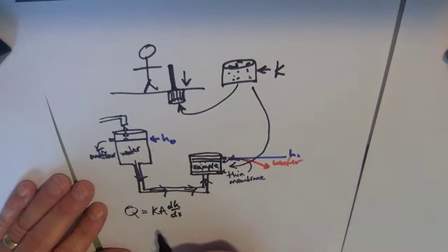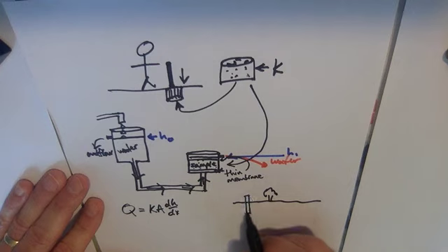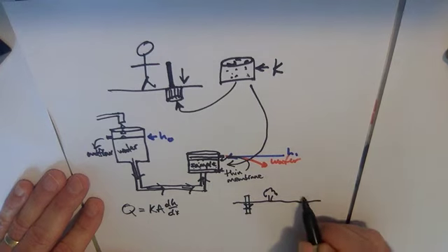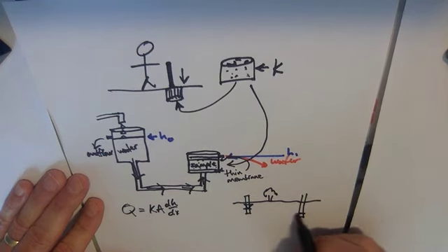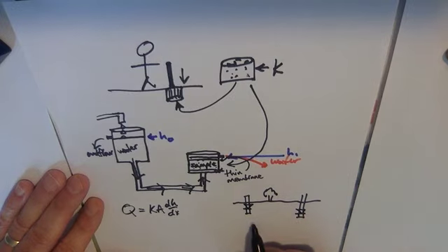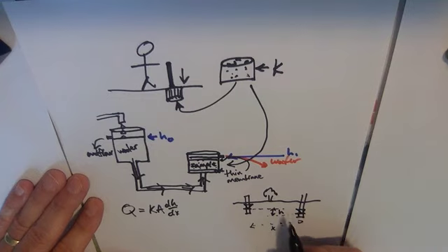All right, so we normally think of dH/dx as something that looks kind of like this, where you've got a land surface here, and you've got a well here where the water goes up to here, and a well where the water goes up to here, and these are some distance x apart, and there's a difference in hydraulic head, h.